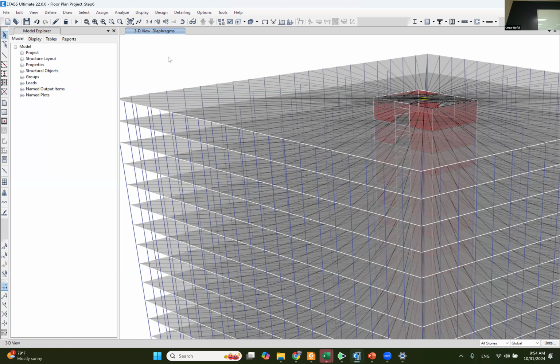Because when we design a slab for live load and say 200 kilogram per meter square, that means two people of my weight are sitting in 1 meter by 1 meter, and that's rarely happening. Okay, so we can do this. The standards tell you that you can reduce the live load on the structure to 25% if it's a residential building. If it's commercial, it's gonna be 0.5 or 0.25 based on the nature. If it's a library, that's 100%. If it's a water tank, we're assuming the water tank is full of water.